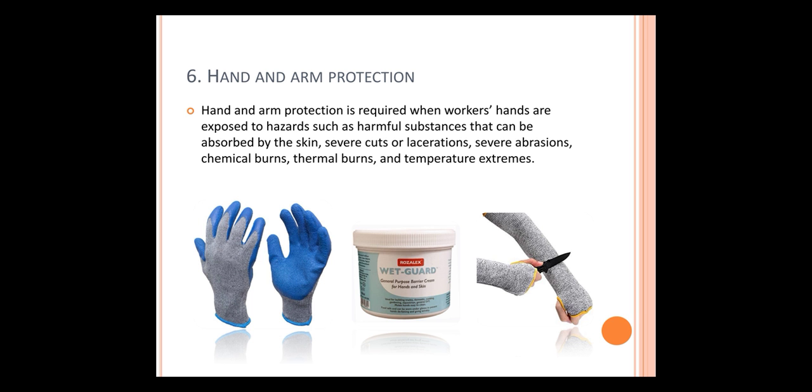There is no one type of glove that provides protection against all potential hand hazards, and commonly available glove materials provide limited protection against many chemicals. Therefore, it is important to select the most appropriate glove for a particular application and to determine how long it can be worn and whether it can be reused.